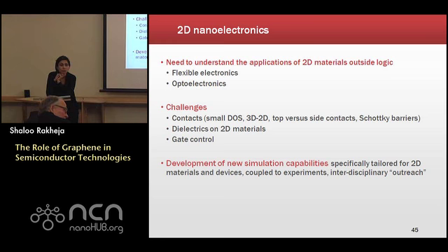So I think in general there is a way to get a handle on the experimental component underlying this contact resistance. I also think that mobility measurements are not being done accurately for short channel devices. I think you have a very nice paper in IEDM that talks about how to do this accurately for short channel devices by removing the effects of this ballistic mobility and things like that.